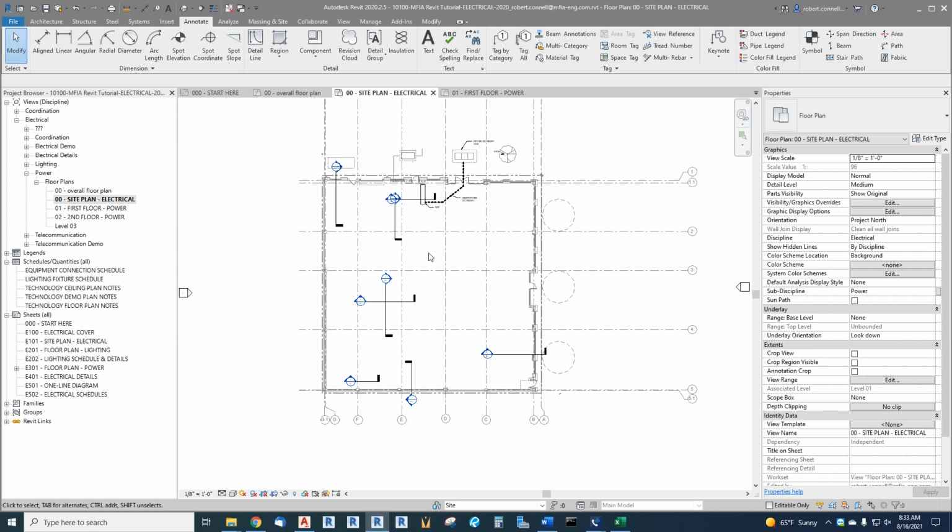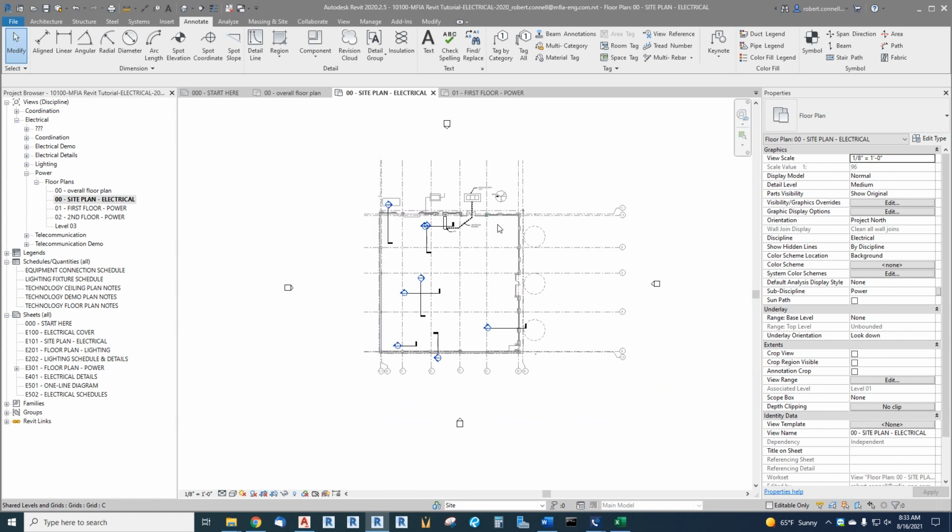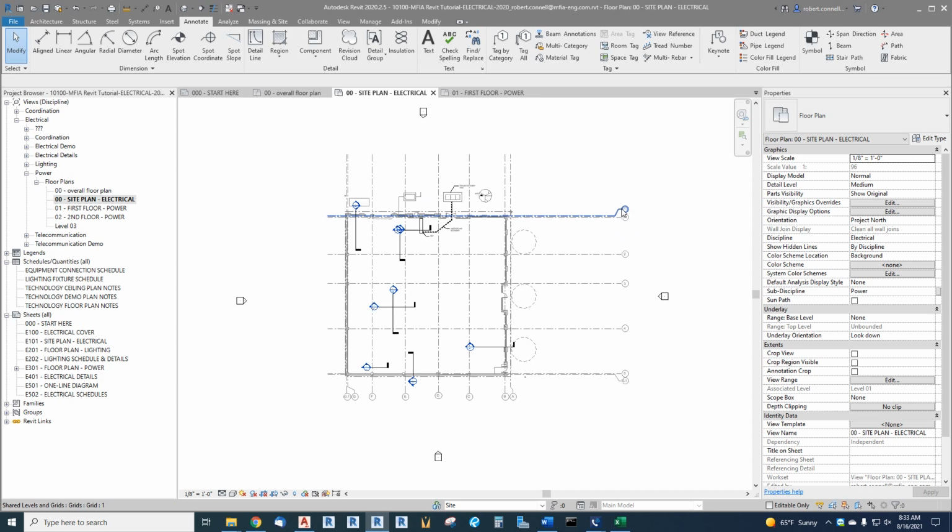So we know how to bring in CAD. We know how to turn layers on and off. We unlinked it from the view template. We can turn grids on and off. One more thing is our grids are way out here, and so if we drag this onto a sheet, it's just going to be huge. It may even be bigger than the sheet. How do we rein in and crop these? We can move them in, but then the elevations will show, things like that.